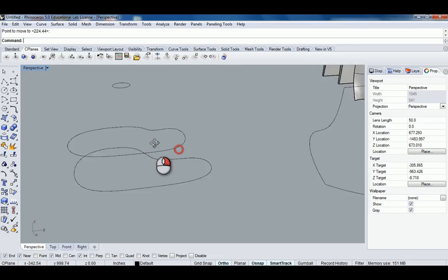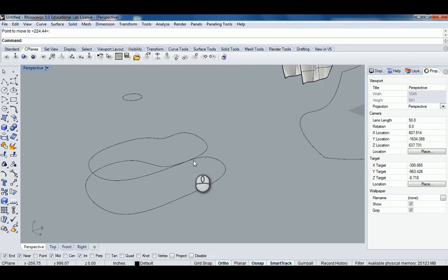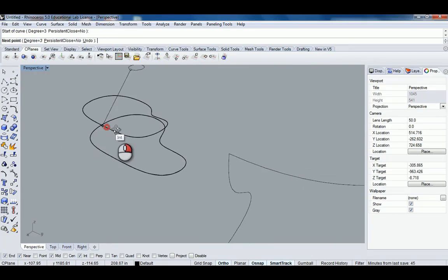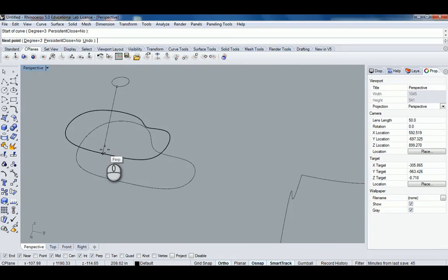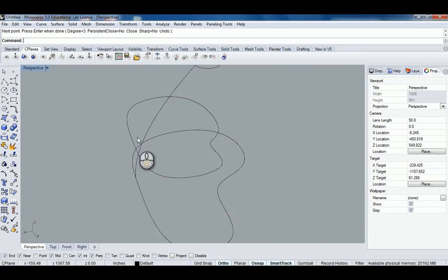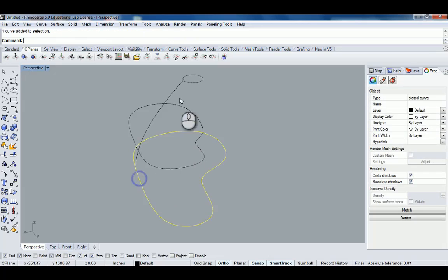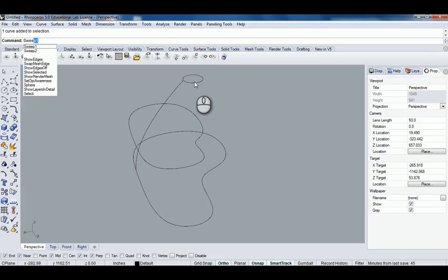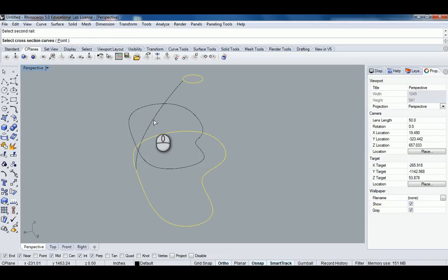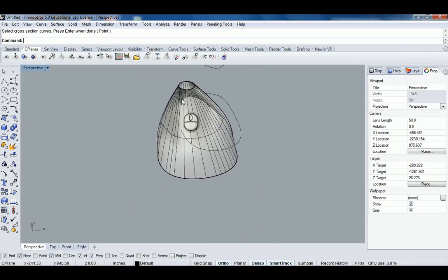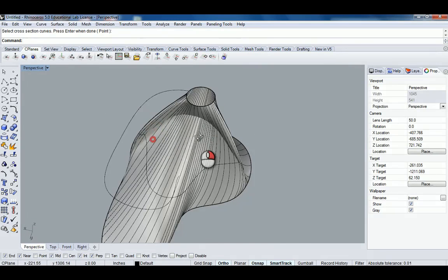Okay, so I could obviously loft this. If I created a cross section, I could attempt to sweep it. I could just make sure that my cross section is going through perpendicular points on this. But then again, it's going to sweep the thing based on the cross section curve, so it's kind of ignoring what's happening in this one. It would only be relating to this. So if I swept this right now, because that curve is wide, it's like inverting on itself a little bit.